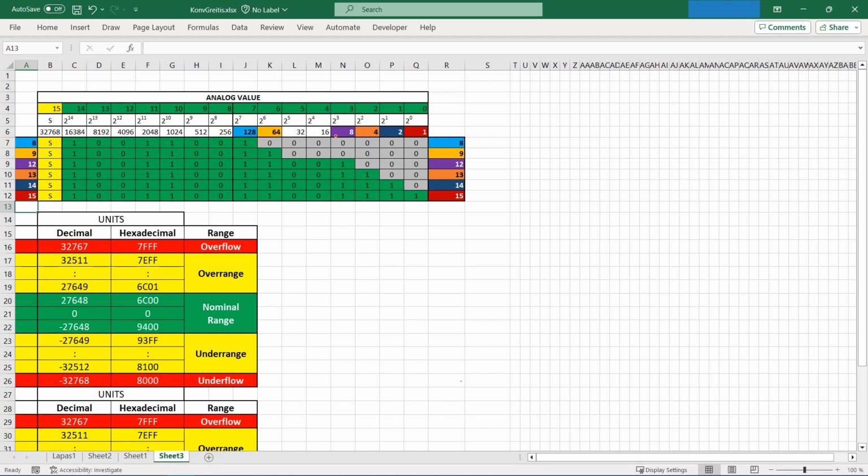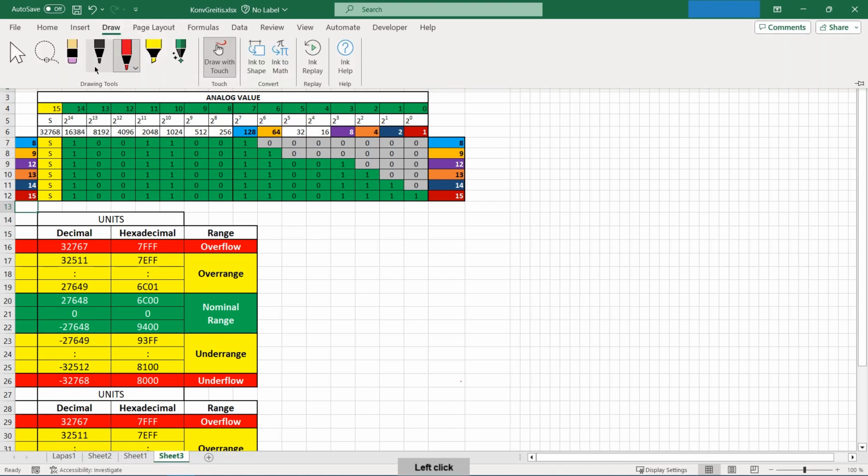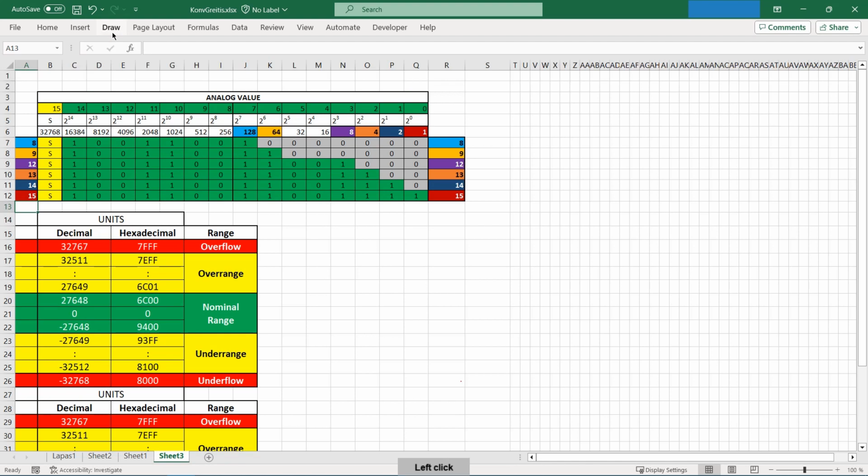Analog input modules convert an analog process signal into digital form, while analog output modules do the opposite, converting the digital value into an analog signal. For example, for analog input, an analog to digital converter is used. This converter approximates the analog value with a step curve.